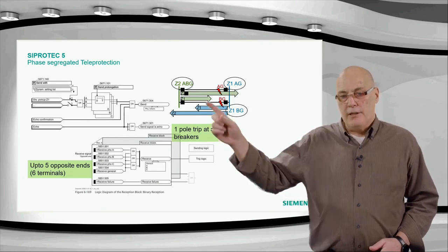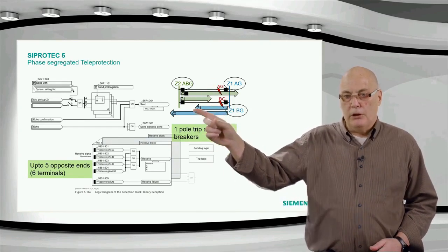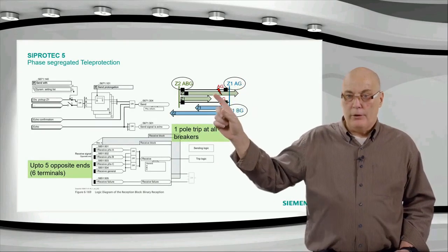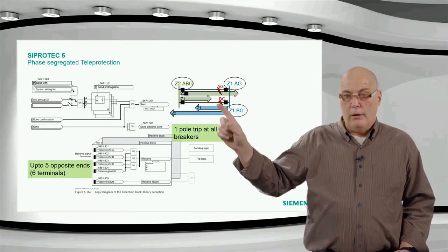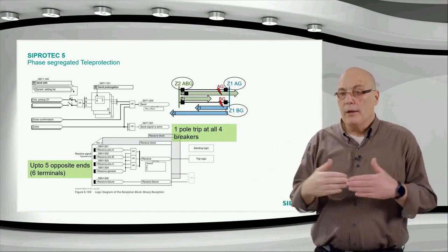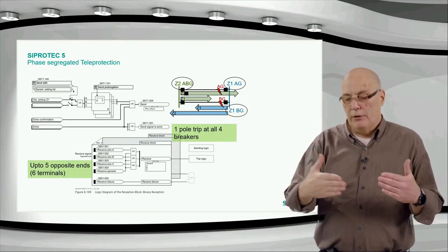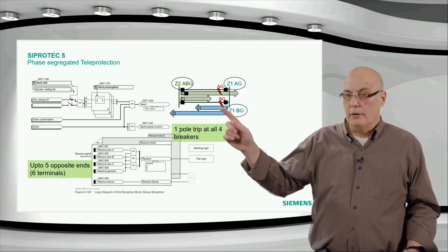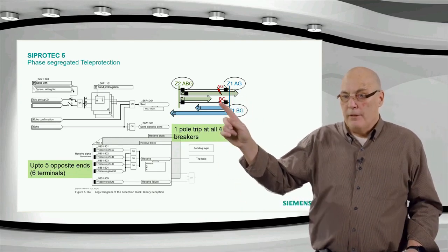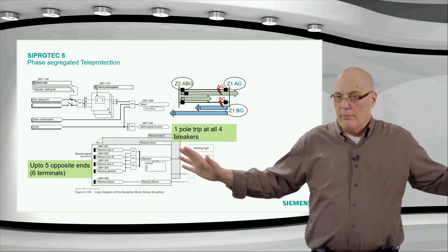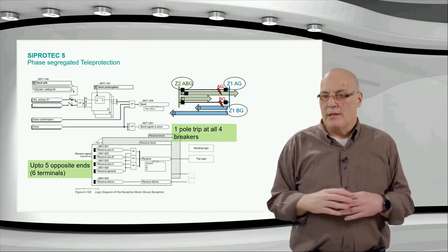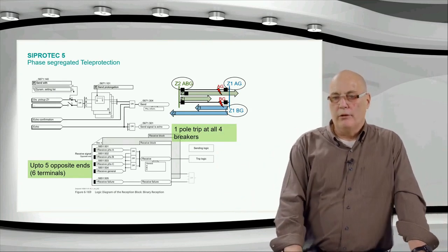Okay, and for this example, we've shown it's the same voltage potential. Maybe they were actually coupled on both sides as well, and you get a fault, A ground on the one tower and B ground on the other tower. It's probably an inter-system fault, where they flash over to the tower, and the arc on the tower burns into the other line. So you get this. Because normally, if these were two independent lines, not on the same tower, the chances of a fault A ground, B ground happening simultaneously is very, very small, very remote.